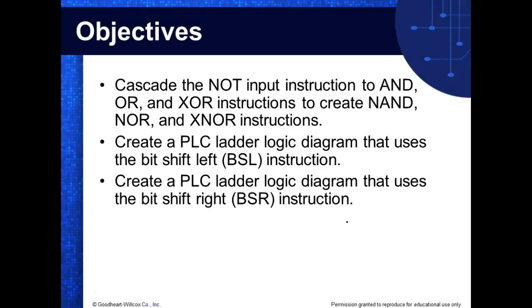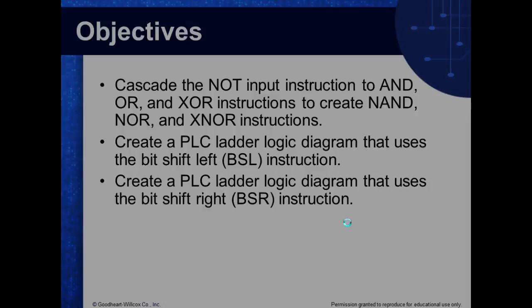We've got 120 volts on the output. So if you want to open up and look at the outputs, you need to put on safety gear. If you're going to make measurements on the outputs, you need to have insulated gloves, right? The 504s, it's 24 in, 24 out.